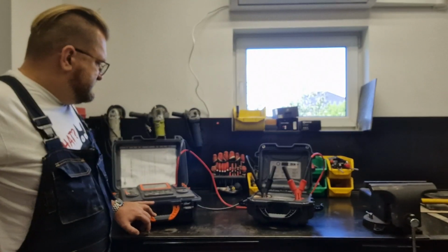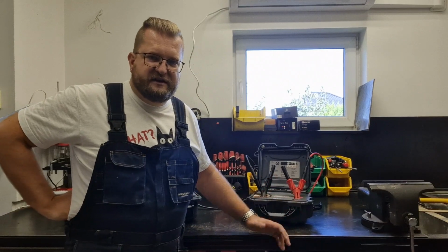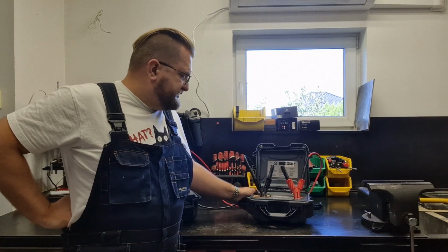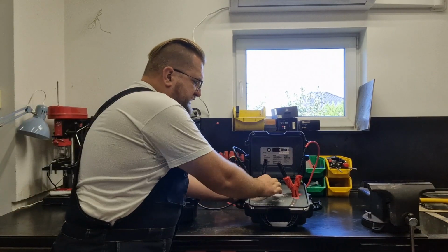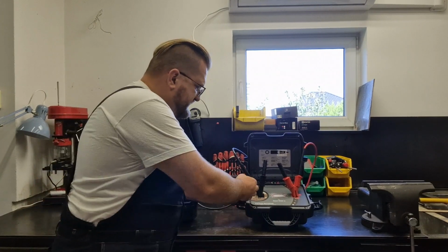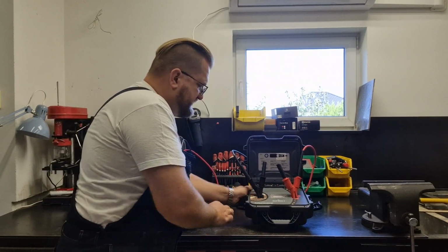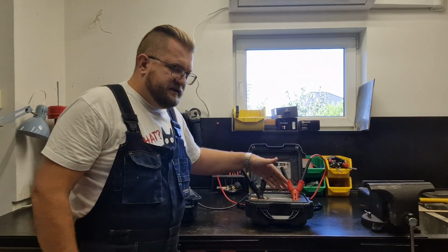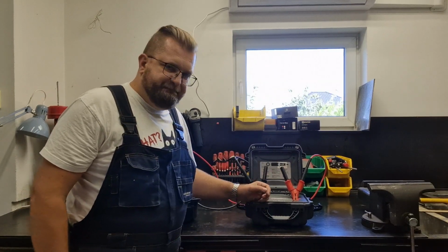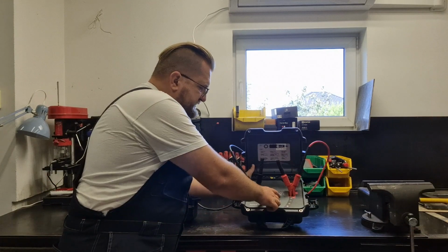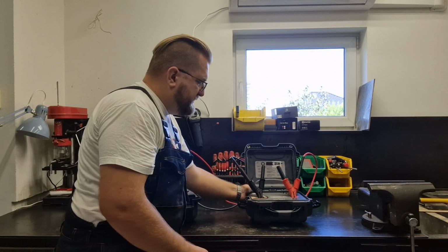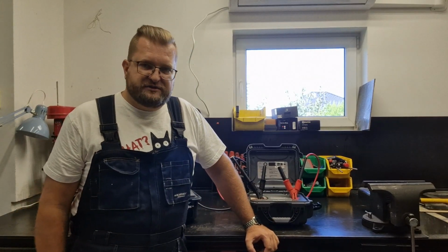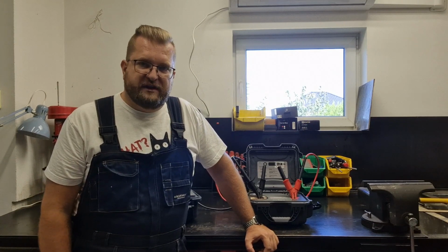But to show this, of course, I do not have a proper cable with some failure inside, so I will use a partial discharge simulator. So this is a cross section of the cable, and we connect the minus to the main core and plus to the shield, and inside there is a structure which simulates the partial discharge. Over here is also a place where there will be visualization of the partial discharge by a diode blinking.